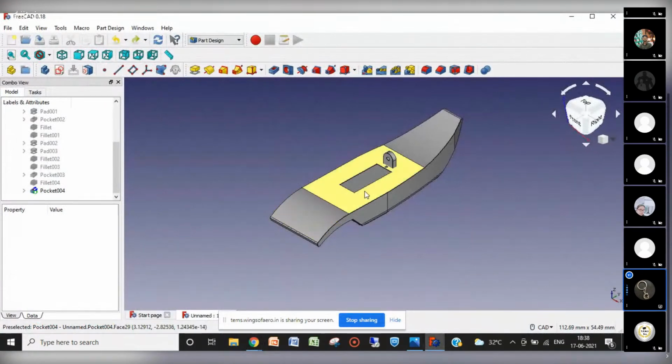And one more thing, this pylon has to carry a lot of weight, so the material is also stronger material for the skin as well as for the struts. Struts are mostly the same for every part of the aircraft, but the skin material would be a bit different and has a lot of joints in struts present inside it.